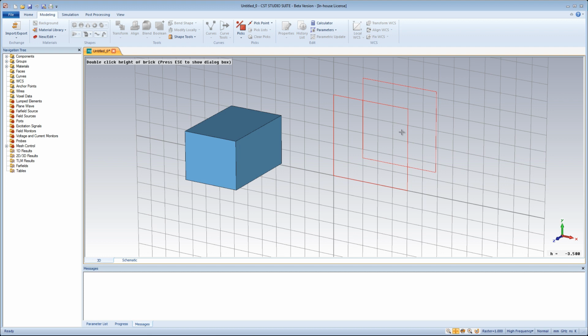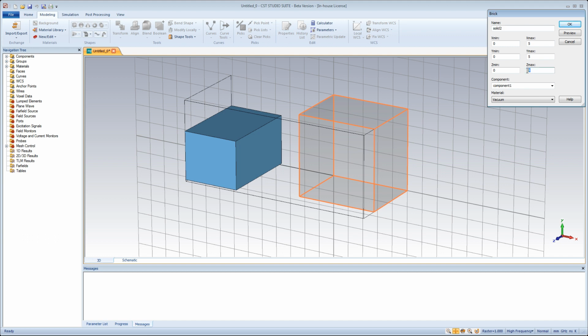The third way to enter accurate coordinates is by clicking the estimated values using the mouse and then correcting the values in the final dialog box. You may skip the definition of points using the mouse at any time by pressing the escape key.